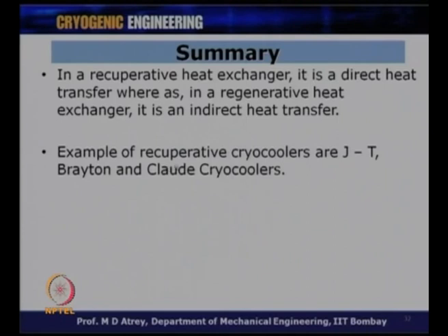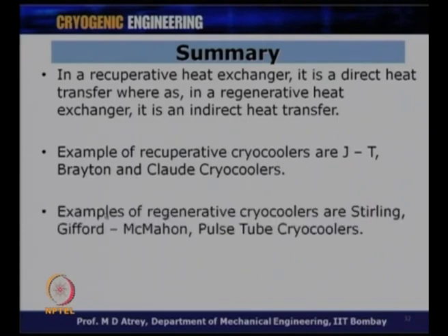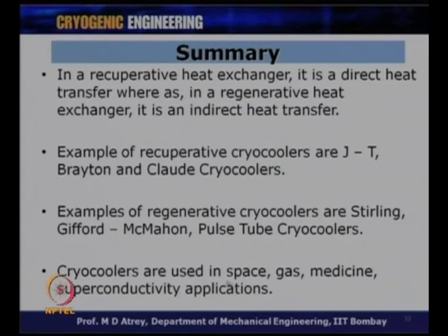Examples of recuperative cryocoolers are JT, Brayton and Claude cryocoolers. Examples of regenerative cryocoolers are Stirling, Gifford-McMahon, and pulse tube cryocoolers which we just saw. The cryocoolers are used in various applications in space, gas, medicine, and superconductivity.